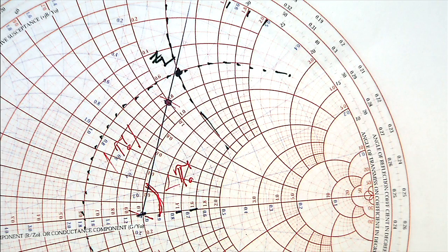And then we need to find the 2 beta D. This beta D you can calculate from 2 multiplied by 2 pi over lambda, and this lambda is C over F, so it is 2 pi F over C multiplied by this D in radians, and then you change it to degrees.